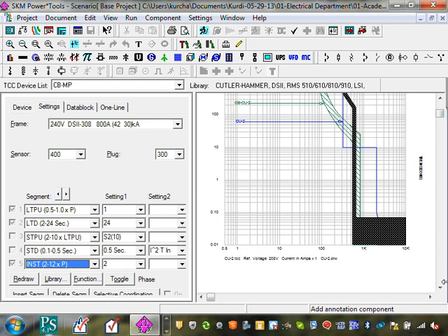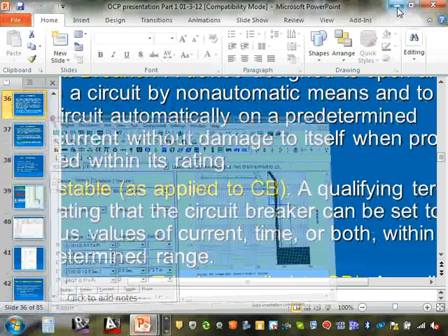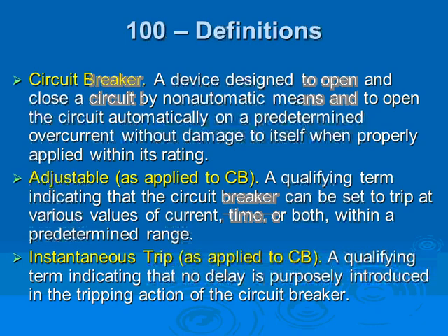So here's your overload, which you talked about yesterday, and here's your instantaneous circuit breaker. The instantaneous breaker will protect you from short circuit, and what do you think the overload is going to do? Protect you from overload. Between the two together, in conjunction, they make a good, complete protection like this. That's your instantaneous trip looking at the short circuit.